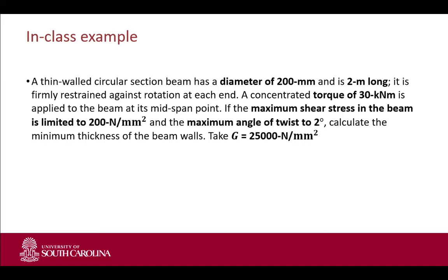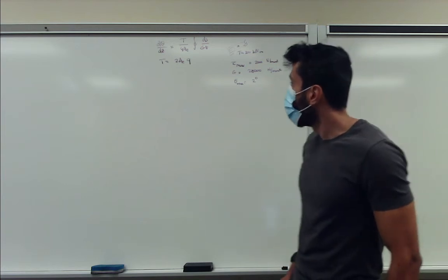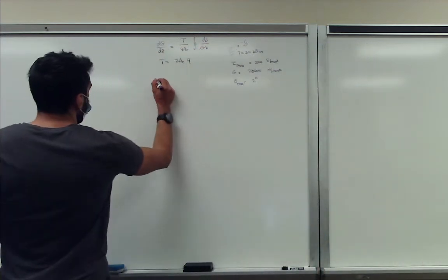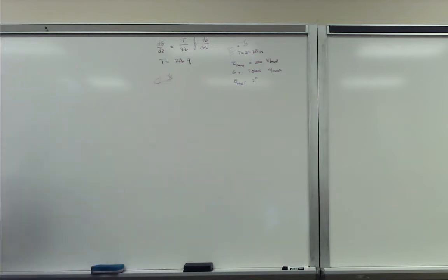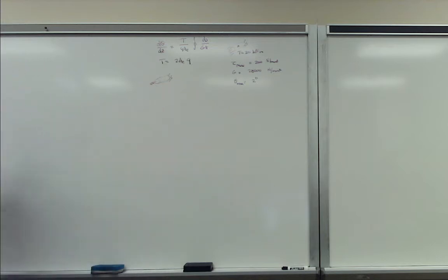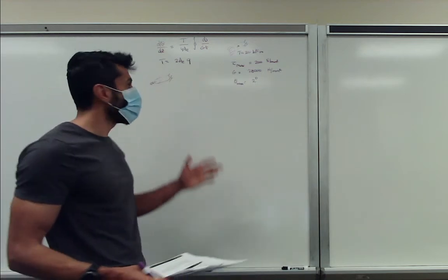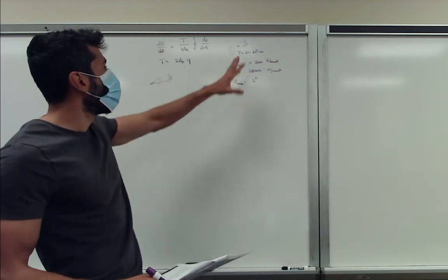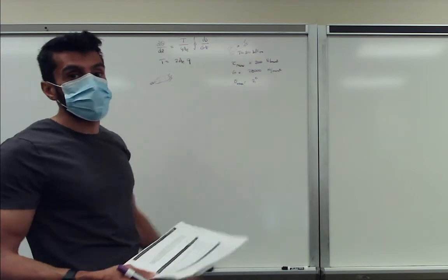So okay, a couple of things before we can actually start. We have to realize these equations are basically derived when we have a torsion beam clamped on one side, and we have a torsion applied at the other end. So this is a beam clamped on two sections. In order to apply this to that, we have to cut it in two and assume that the torsion is equal on both sides.